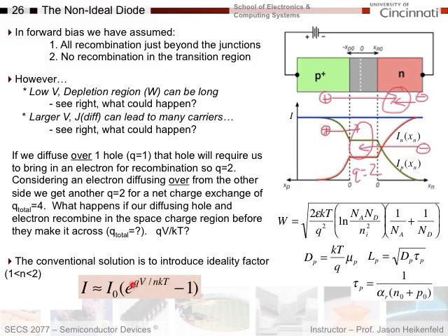However, if you're at really low voltages or very high voltages where recombination in the depletion region can occur, then n could get to as great as 2 because you're going from a Q of 4 to a Q of 2, right? And so then n makes this half as efficient. And so for a given voltage, in a given charge, you're only half as efficient at generating current. Because again, if it's Q I'm measuring and it's coulombs per second, then if I have less Q, I have less current. And so that's how we introduce that into the diode.